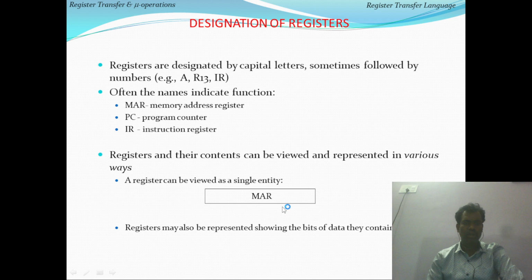So after executing the first instruction, the next instruction address may be the second instruction, or it may be the 10th instruction address. That can be kept track of by the program counter. And the memory data register holds the data within that memory location; the value stored in the memory location will be transferred to the memory data register. So address and data are the two basic representations of any memory.